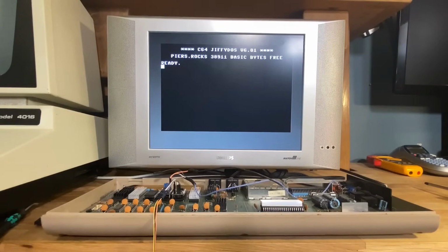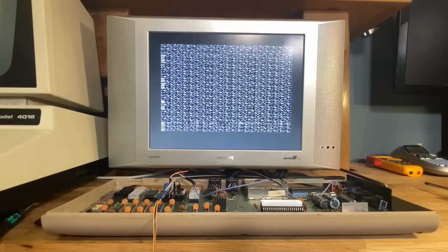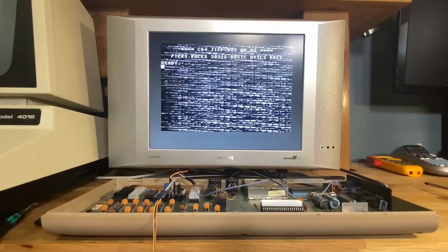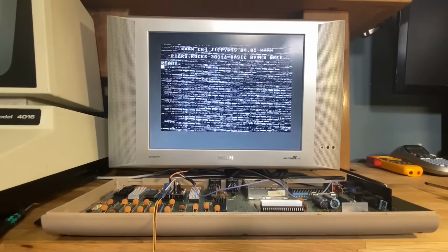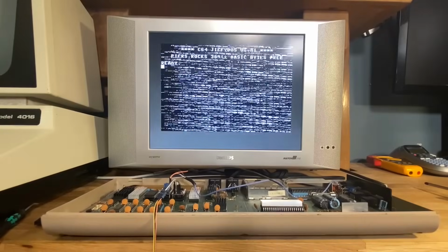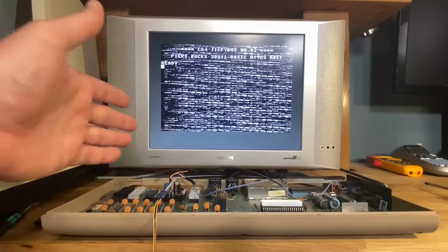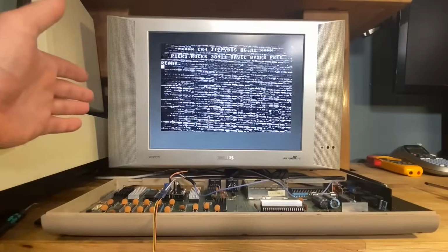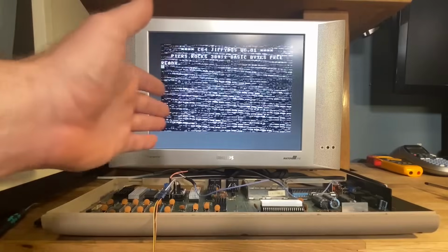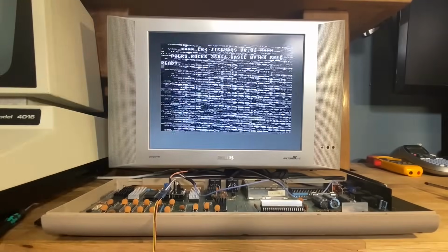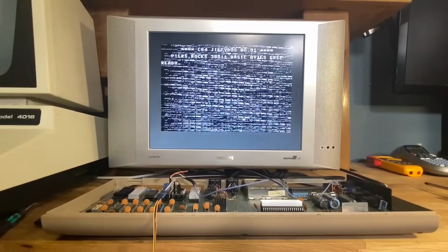So it's downloading the images again, it's building the firmware image, it's erasing and programming, and it's done. Right, so we're seeing a whole bunch of weird artifacts on the screen. That's essentially because in a whole bunch of cases, the software-defined retro ROM is serving the byte just a bit too late, just outside of the timing specification for this ROM type. That's with 80 megahertz.